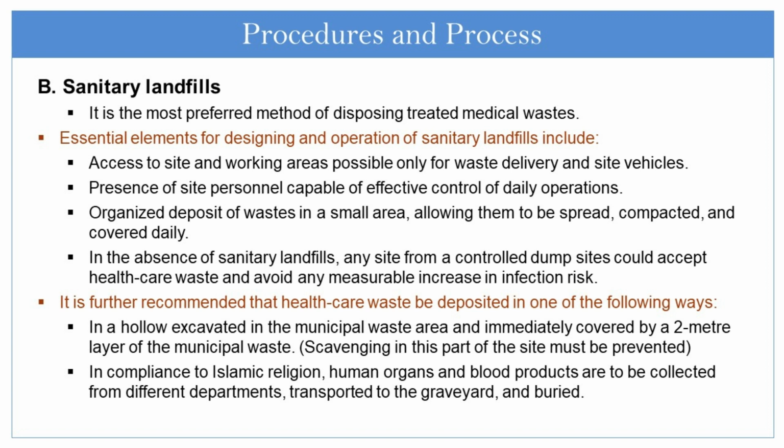The presence of site personnel capable of effective control of the daily operations should be there, and organized deposit of waste in a small area, allowing it to be spread, compacted and covered daily. So if you go to a sanitary landfill, there is proper daily compaction and cover going on. In cases where there are no sanitary landfills, any site from a controlled dump site could accept healthcare waste to avoid any measurable increase in the infectious risk.